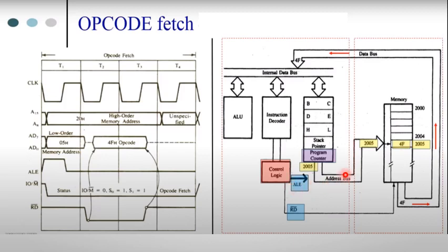We know that the address bus in the 8085 is 16 bits, and that the 8085 has a dedicated higher order address bus A8 to A15 and a multiplexed address and data bus AD0 to AD7. In order to demultiplex these address and data lines, the ALE signal should be enabled. As this ALE signal goes high, it demultiplexes the address and data lines.